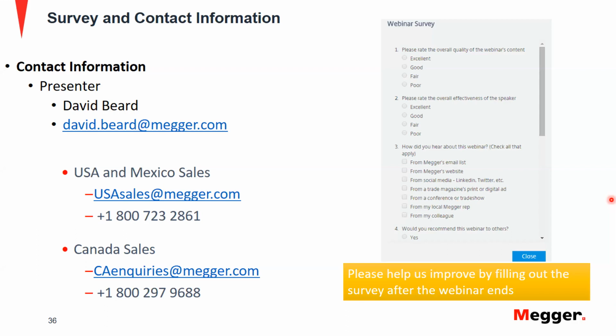Beautiful, thank you. So Mohit, I have a question for you. Can overcurrent elements misoperate for faults not on the protected line? Yeah, absolutely, especially on radial feeders. I'm assuming the question was asked related to non-directional overcurrent elements. Non-directional overcurrent elements, no matter what the direction of the fault is, if the value is higher than the pickup, the relay will trip.